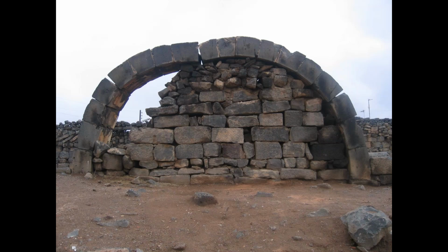And here we've got a quite rare example of an arch. It's not an arch bridge, but it's an arch where we've actually got these 4 hinges present, and to prevent the arch from actually collapsing, somebody's infilled underneath the arch, so we can sort of see it hanging there pre-collapse.